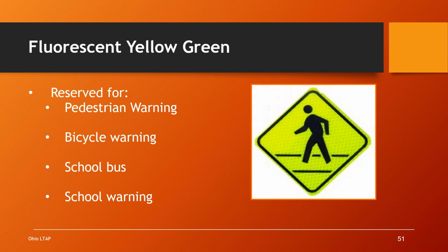So it's important that we communicate that there's workers in the roadway, and if you're not going to use the sign, that it's important that the workers have their fluorescent yellow green vests or shirts on, and that they're not faded. They're still very vibrant, very colorful. In fact, some of the tags on workers' apparel tell you that you're only going to wash it like 25 times max, and then you get a new shirt. That's what you're supposed to do on some of the apparel.